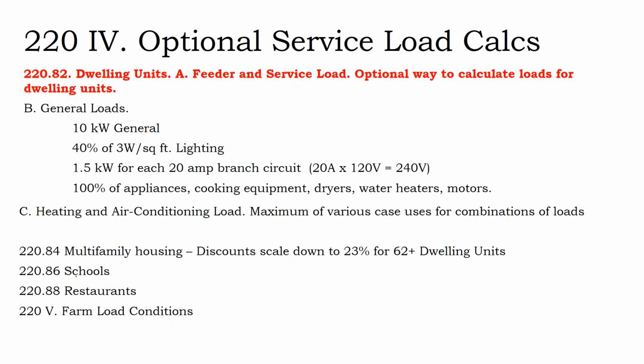So when you're determining, if you're doing a microgrid design, you want to determine the smallest electric service. This is why builders will just put in a 200 amp service, even though for one particular customer you look at their power draw and their electric service could go all the way up to 50 kilowatts, but they're never getting above 4 kilowatts. So why are we giving them a 200 amp service instead of a 100 amp service? Well, code is not looking at all of your on-site optimization. It's trying to set a minimum rule of thumb.